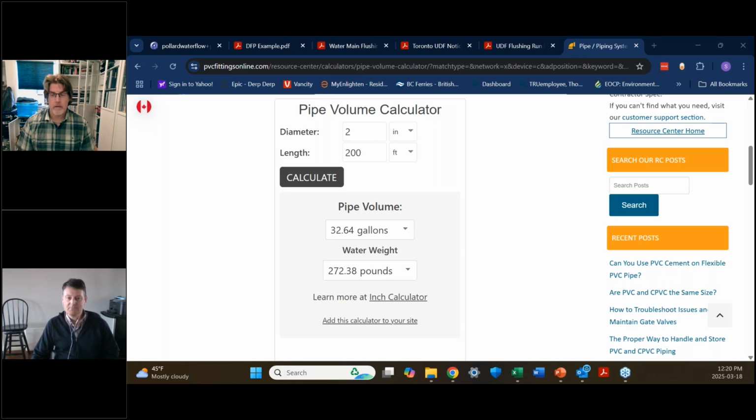We have another question here. What is the immediate remediation if pressure goes below 20 psi for a non-chlorinated system? If it is a quick little blip, maybe you don't have an issue. But anytime you notice that this happens in your system, I would talk to your drinking water officer and explain what happened. We were doing flushing, and we noticed that the pressure at this section of our system went below 20 psi for the period that we were flushing. Follow direction from your drinking water officer. They will be able to come in and give a better assessment of what the back siphonage risk was in that system and what procedure they would like you to follow.